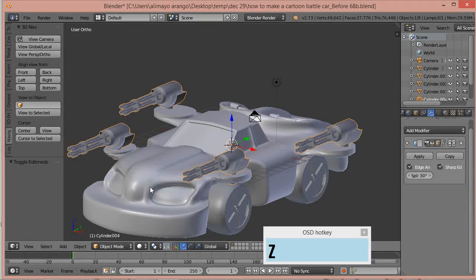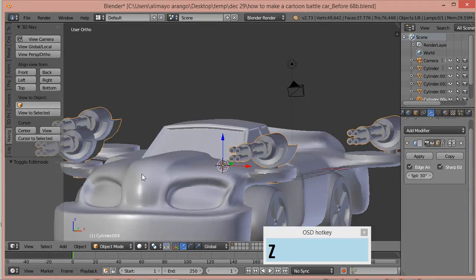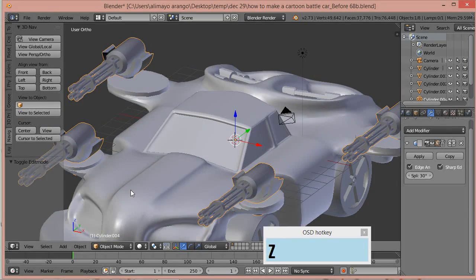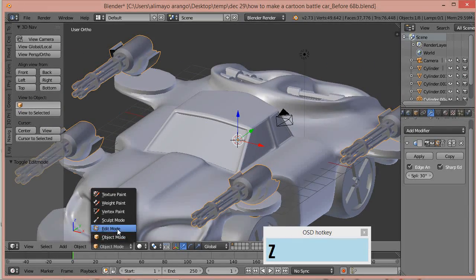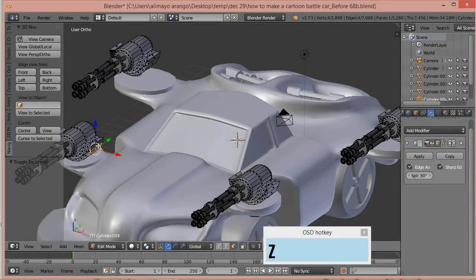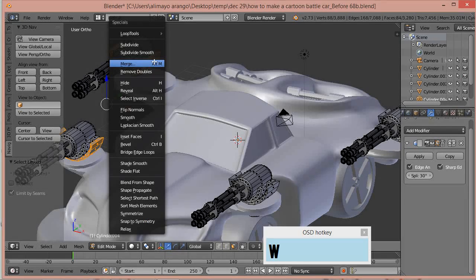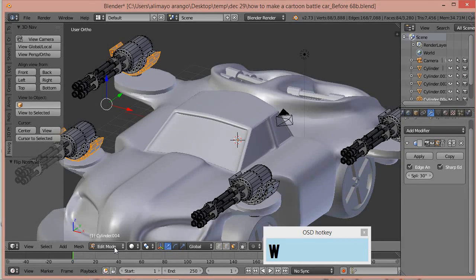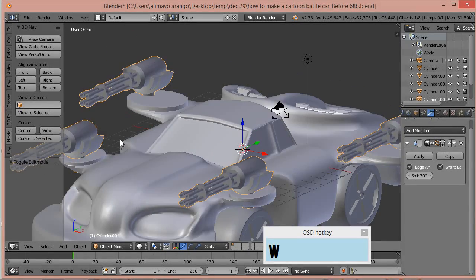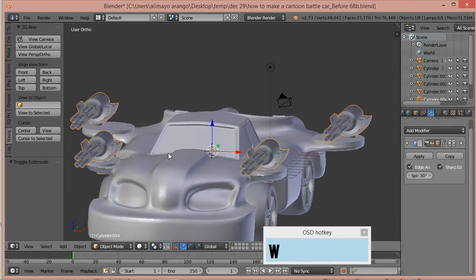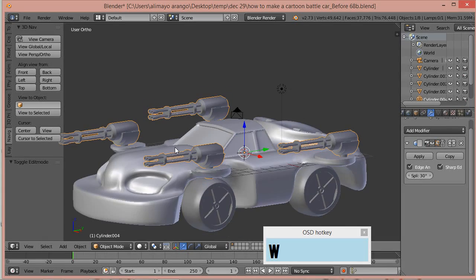Trying to go to object mode, my brain was thinking... still doesn't look right. So for this thing, we're gonna click here, go back, we'll select here, we'll press L to select this whole part here, and L there. Now we're going to press W, and we're going to go to flip normals, and that looks like it did the trick. So now we go, yeah, that did it. So the flip normals were needed to get that looking right.